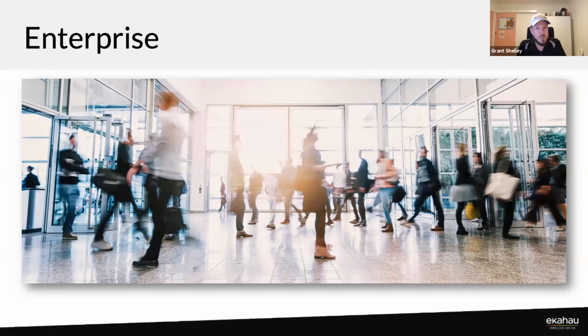Well, I was also just going to say with enterprise, I know we're using a stock photo there, but that's a lot of open space and a lot of glass. In enterprise office type environments, the last webinar I was on for the autopilot survey, that was a big open office environment, and they were just using Omnis with 80 MHz wide channels everywhere. So you could probably guess what the main issues were in that type of scenario. I think there is still value in doing that AP on a stick scenario, because you may be shying away from using Omnis and looking to use some more external antenna type scenarios because you need to cover for density rather than just outright coverage.